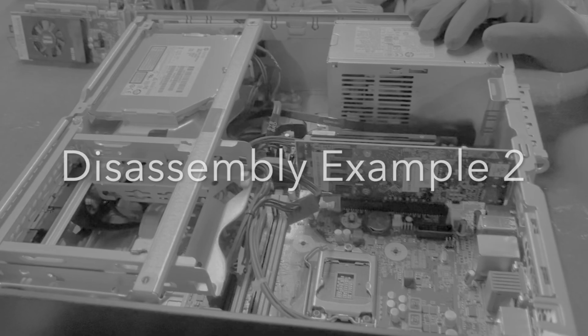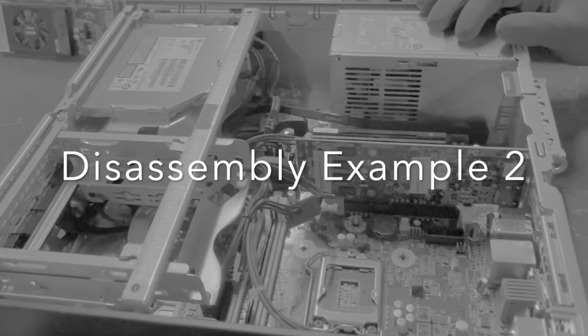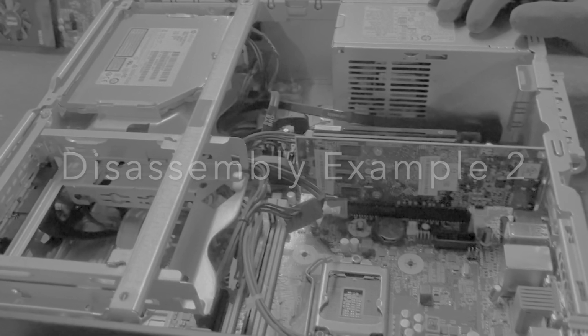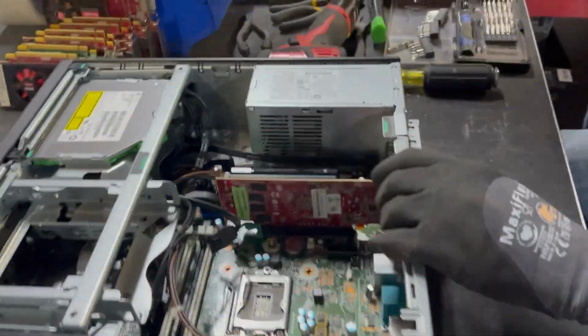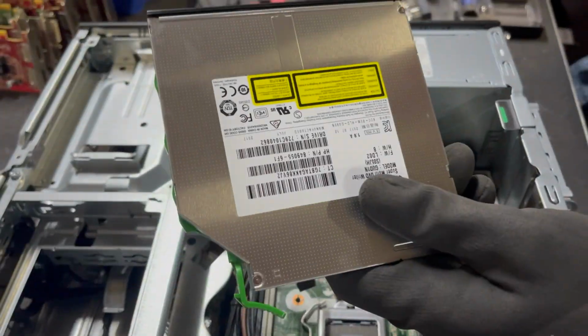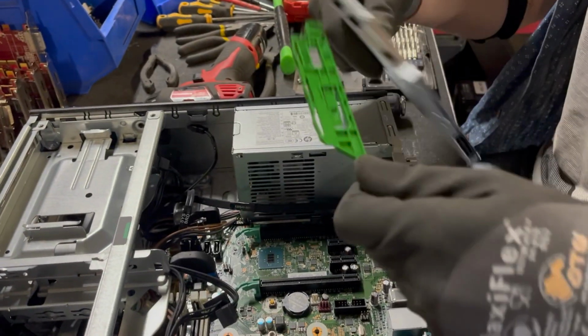At this facility, the hard drive, RAM, and processor chip are removed by the intake technicians before being sent for disassembly, and the technician sorts the remaining materials into various containers as they are removed. The fan and plastic parts are removed first, then peripheral boards are unplugged from the motherboard. When the optical drive is removed, it is checked for any disk that might be in the unit, and a small controller board is removed.